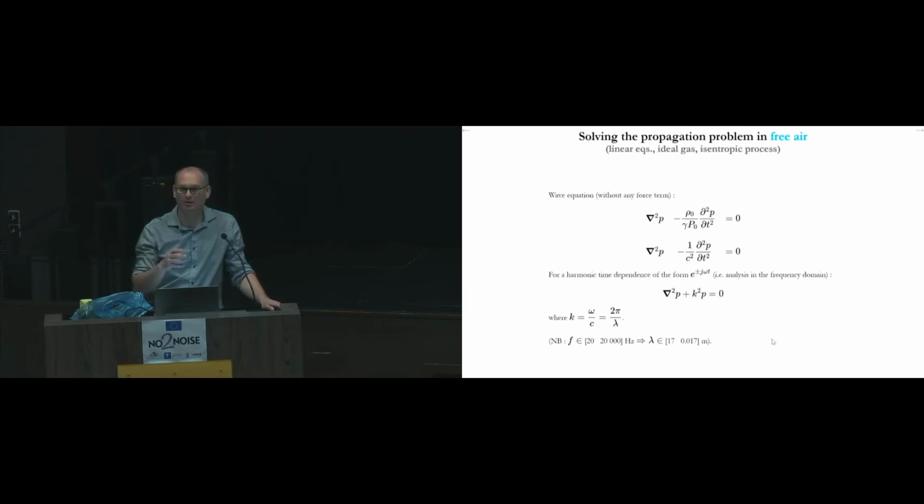So this explains why it will be difficult to absorb sound or to isolate a room from sound with a partition which is only some centimeters thick, because at low frequency we have a phenomenon with a wavelength of 70 meters, and it won't be stopped by something which is only some centimeters thick.